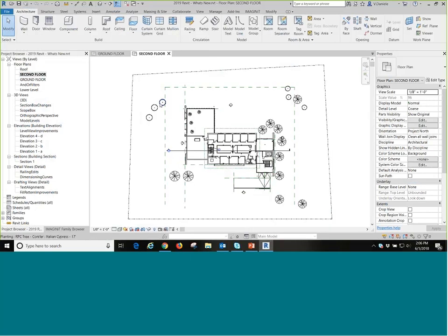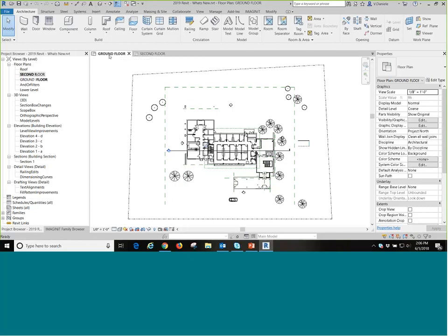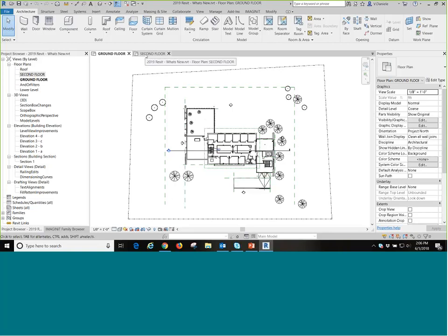When you double click to open up a view like you normally would in Revit, instead of just opening up that new view on top of the previous, it adds a tab to that whole view screen or the whole view window. So now switching between open views is really easy. You don't have to use your hotkey Control Tab to switch through views. You can just go right to the tab, and you can have multiple views open across this view window. Let's jump back to this.